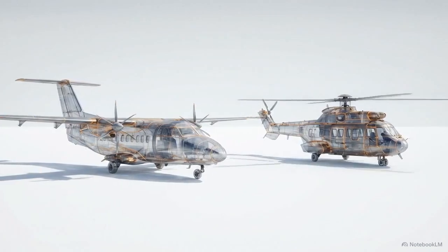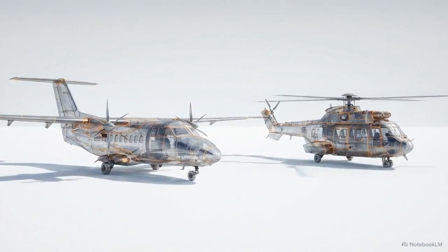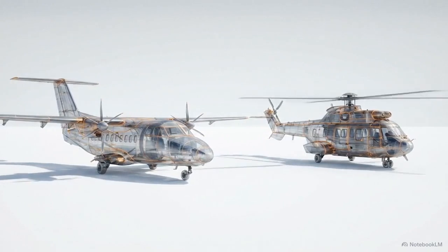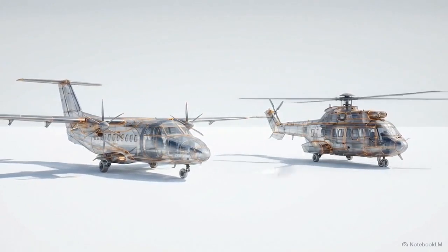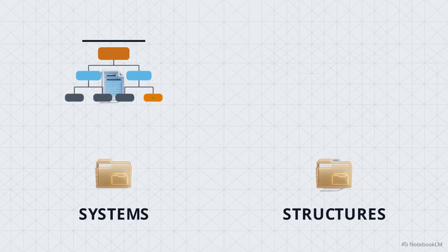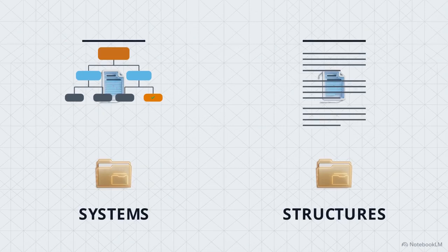MSG-3, Volume 1 for fixed-wing aircraft, and Volume 2 for rotorcraft provide the industry-wide standards for developing scheduled maintenance programs. For years, the systems section of these documents utilized a specific, rigid procedure for identifying maintenance-significant items. However, the structure section lacked a similarly standardized selection process.